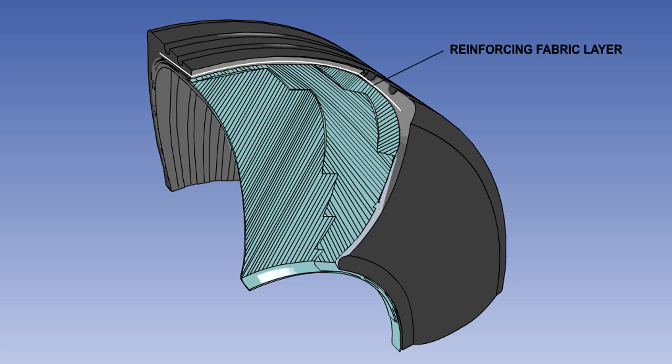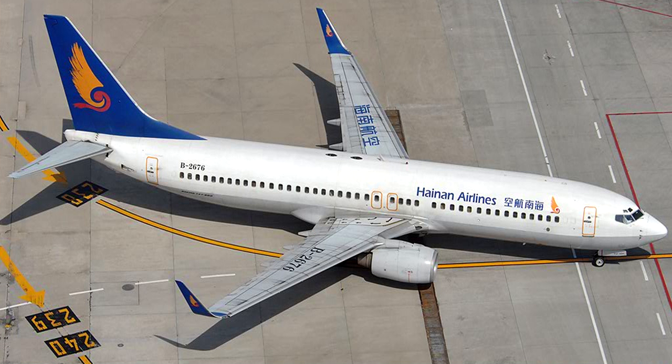For special high-speed applications, some tyres have a layer of fabric woven into the tread. These tyres will have reinforced tread printed on the sidewall. This fabric may become visible during normal wear. This is perfectly normal, and the tyre can continue in service with this layer visible. With the increased size of modern airports, taxi distances have also increased, thus increasing the amount of tyre wear and risk of damage. To minimise tyre wear, it is recommended that a speed of no more than 25 miles or 40 km per hour should be reached during the taxi run.